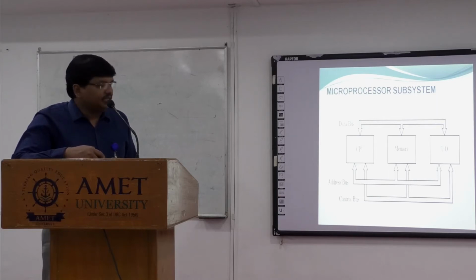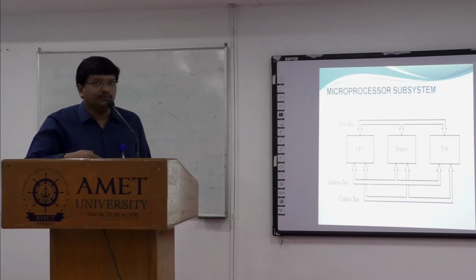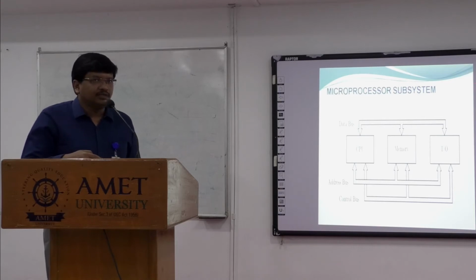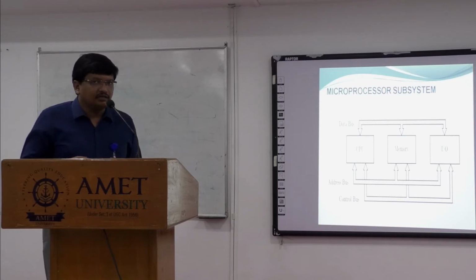Buses can be majorly classified into three types. What are they? They are address bus, data bus, and control bus. As the name defines, the address bus is used for exchange of addresses from one module to another. Next is the data bus, which is used for efficient transfer of data between one module and another. Finally, the control bus is used for controlling the operation of all three modules.